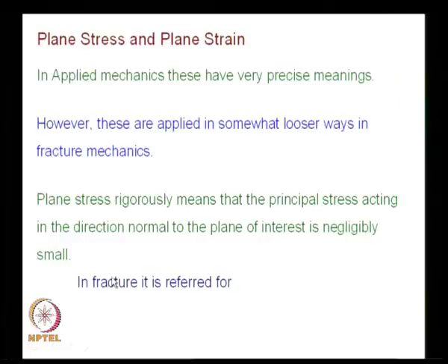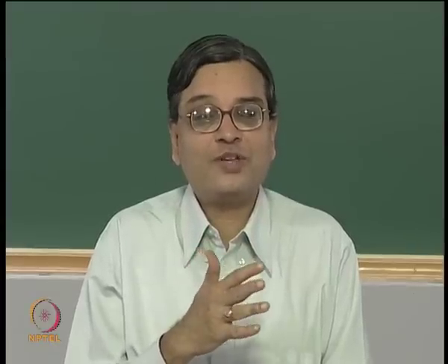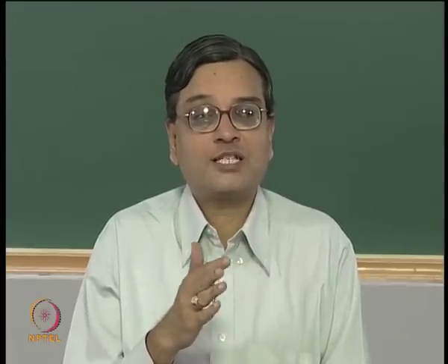In fracture, what do you call plane stress? It is referred for thin components with in plane loading, and we also do one more thing. We say the surface layer of thicker components behave in a plane stress fashion. This is something unusual. This is so convenient for us to develop certain concepts in fracture mechanics.